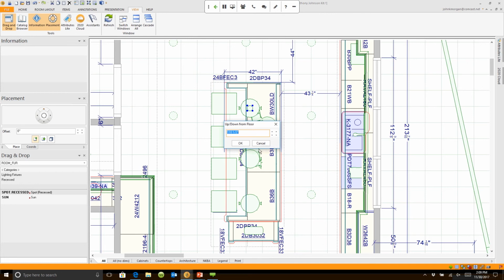Well, this shouldn't be in the ceiling. It actually needs to be light emanating from inside of the light fixture. So I've already gone in and tested this, and the light itself should be at 75 and 5/16 inches off of the floor. I'll change that. These are all things you're probably already doing.